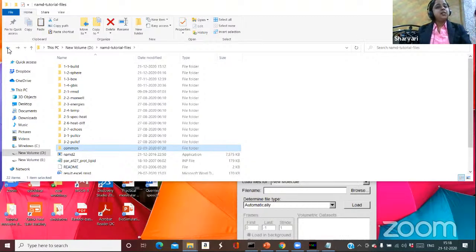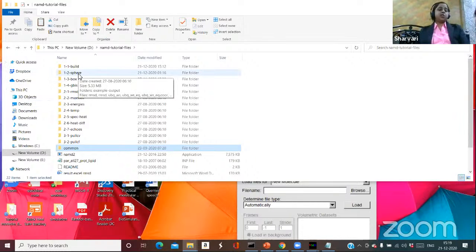So we are going to keep a single common directory where we are going to copy, listen to me carefully, ubq underscore water sphere pdb, ubq underscore water sphere dot psf, and our other files we have in 1.1 build. So you need not copy these two created files separately. Copy the normal UBQ PDB file, the UBQ underscore water sphere PSF file, and the UBQ underscore water sphere PDB file. Once this is done, we will see how to run the simulation in the sphere.